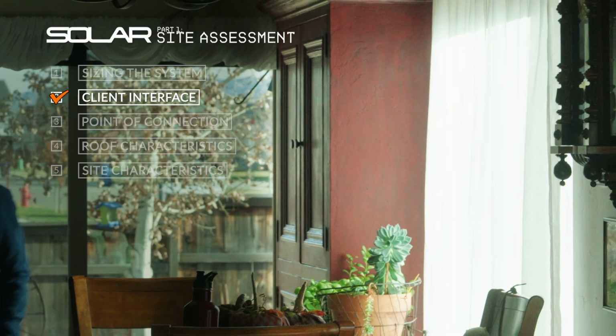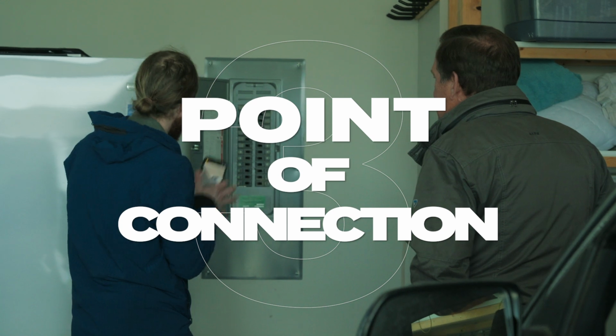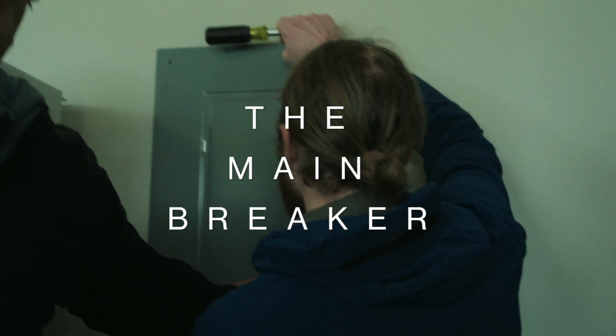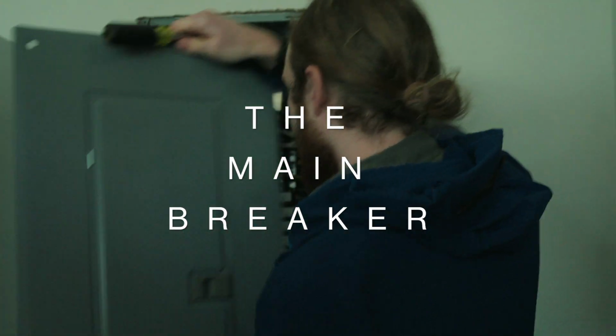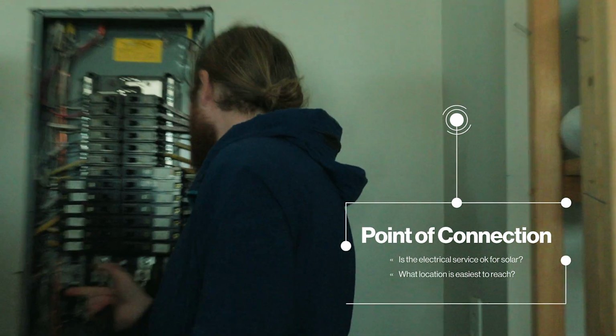All right, let's check out your main house breaker, please. You don't need to be an electrician to assess the point of connection for a PV system. We're trying to find out where we want to interconnect the solar to the grid. We're looking for two things. Do we have at least 200 amps of service? And can we reach a service or sub panel easily from the roof?